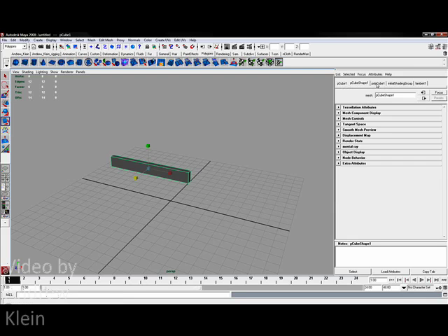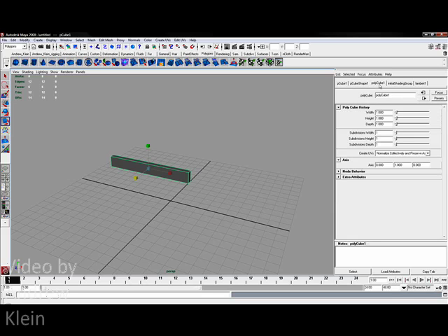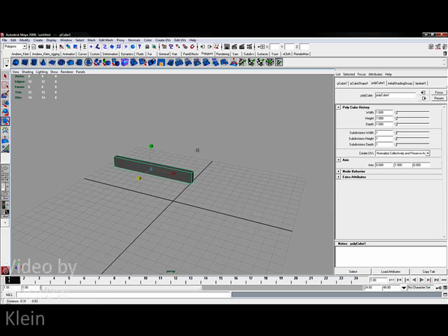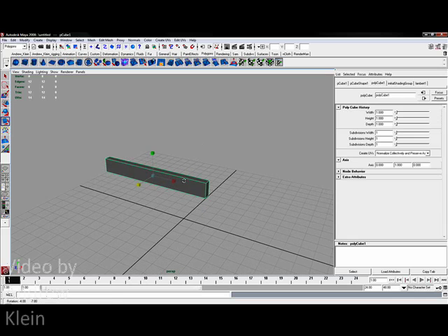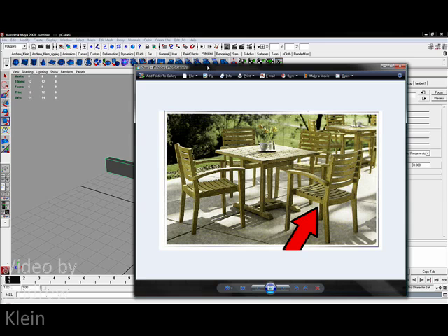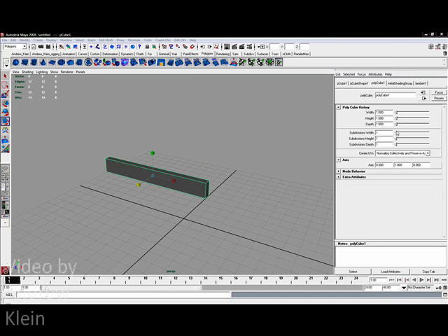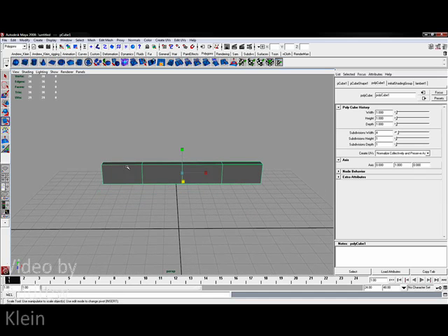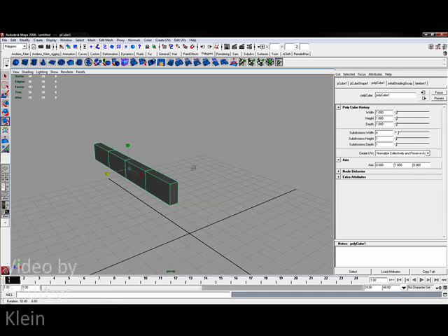In the middle tab of the attribute editor, you'll see Polycube 1. This is your initial creation attributes. Here's where I can alter the number of subdivisions for the width, for the height, and for the depth of this cube. Well, since I want to add just a couple of divisions going in the direction you see here, that to me looks like I need to add 4 divisions to the width. And as you can see, 1, 2, 3, 4. It counts the faces across.